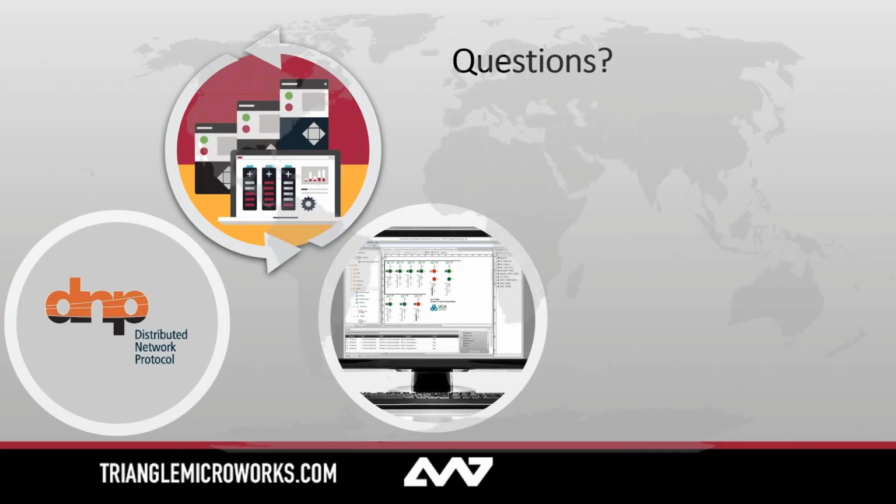Okay. How do you check responsiveness and latency? So we did that today using the JavaScript, right? With the JavaScript, you can monitor the initial time that your initial conditions were set up. And then after you get through the entire fleet of tests, whatever you're checking, you can then determine an end state and find the difference there. That's how I was getting the 100 milliseconds, 150 milliseconds I was showing with the gateway mapping tool. That's how I was getting the 2 seconds with the recloser tests.